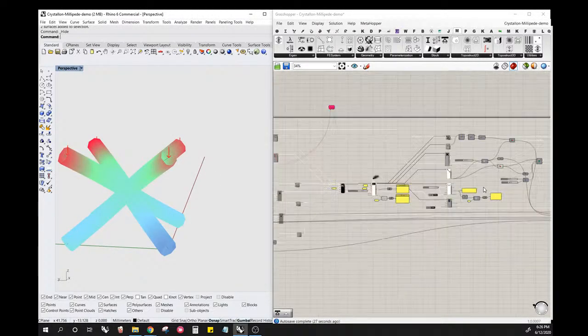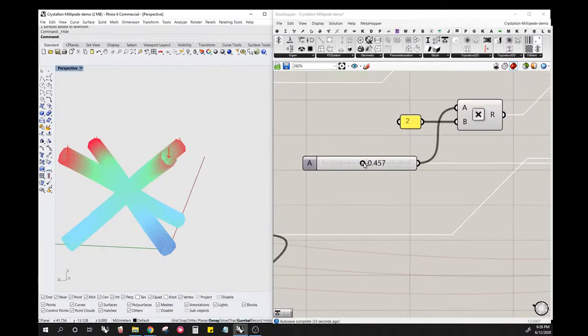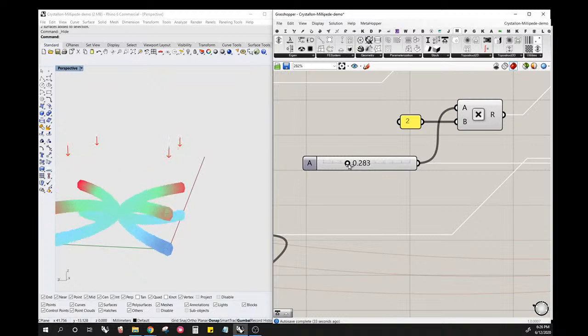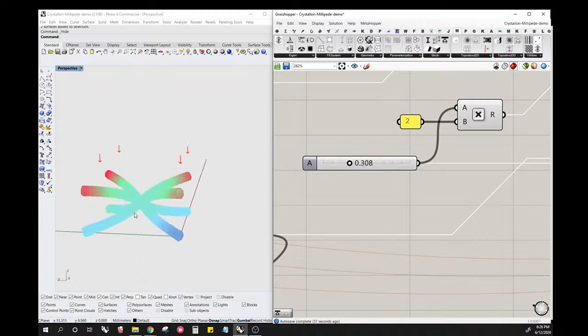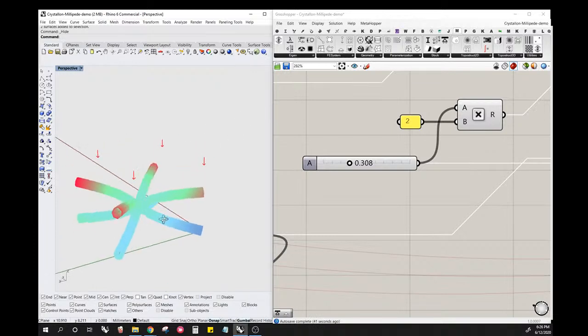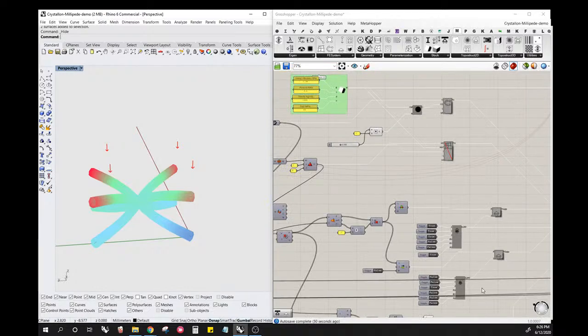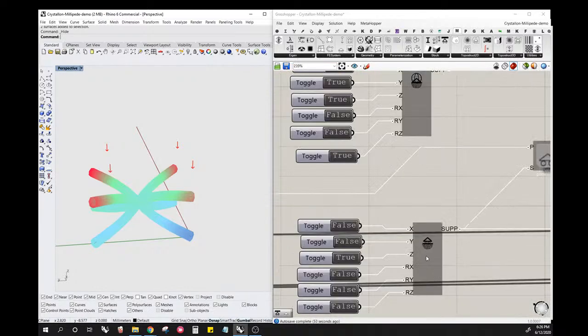What I wanted to show you real quick is, let me make this a little thinner so we see a lot of deflection happening. I want to show you how changing these boundary conditions actually changes our model quite a bit. Right now it's moving freely on the bottom surface, because these supports are free to move in the x and y direction, and they're also free to rotate in the x, y, and z axes.